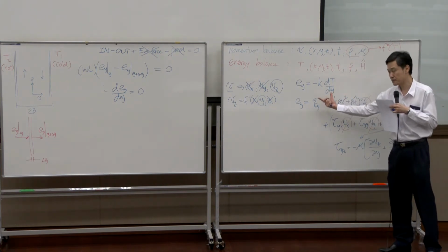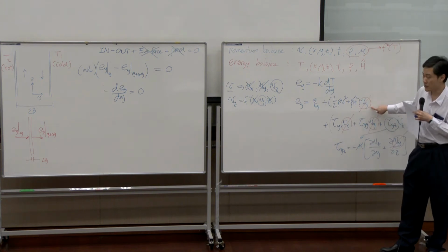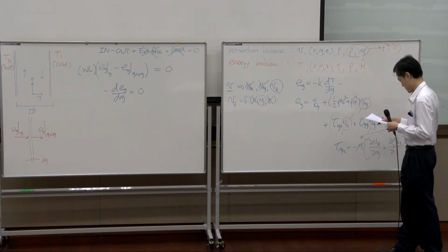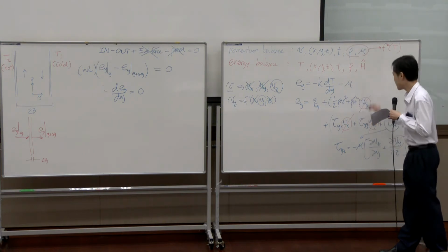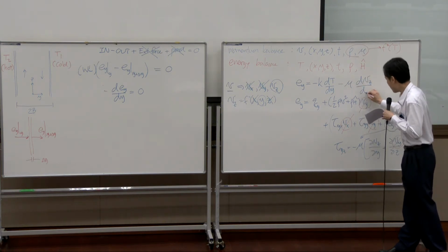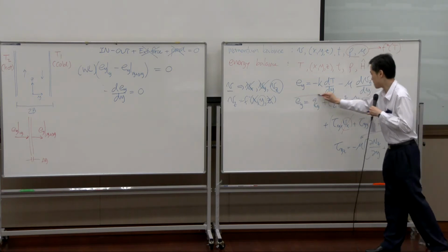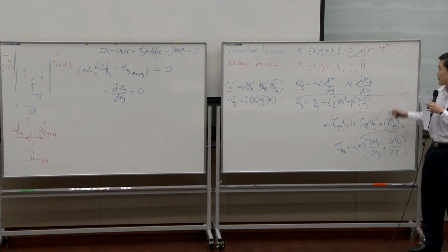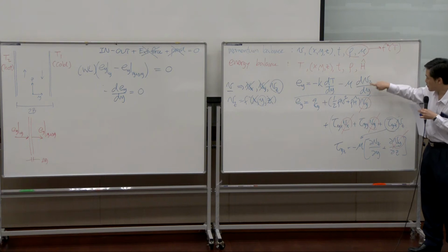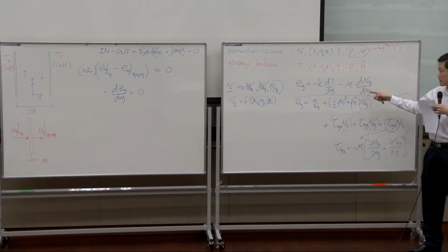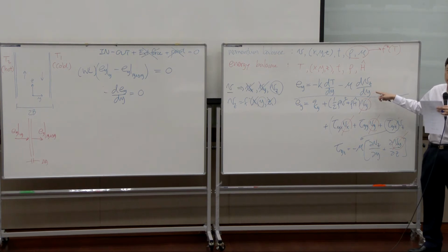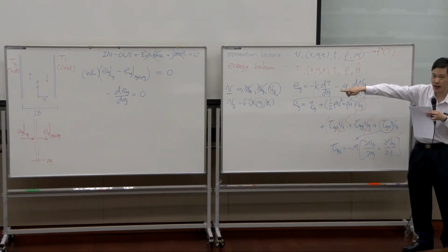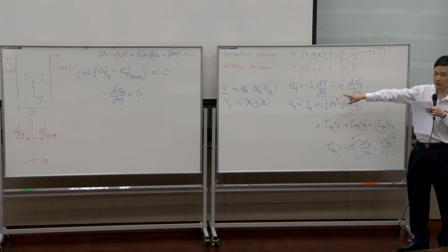That's conduction term. This term is 0, convection term is 0. Flow work term, you have only one term left, which is minus mu here, dvz by dy. Okay? Now, I changed this Vz, differentiation of Vz into total differentiation because Vz is function of y only. Then you can bring this equation to that shell balance and solve for temperature profile.